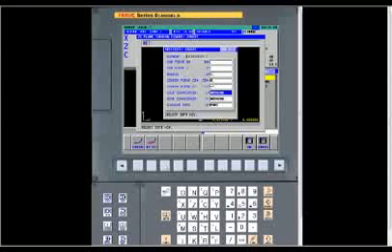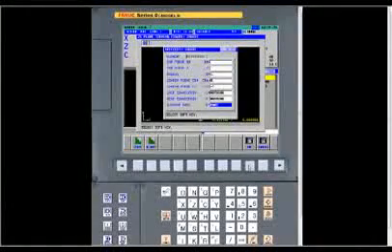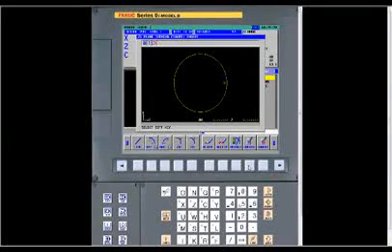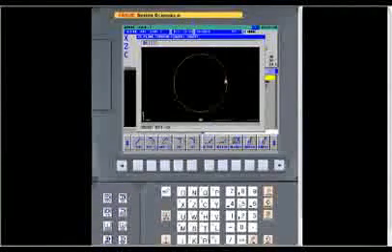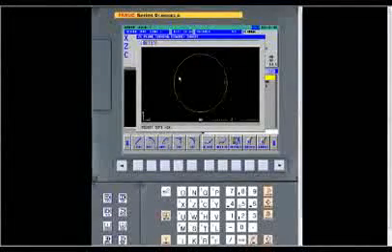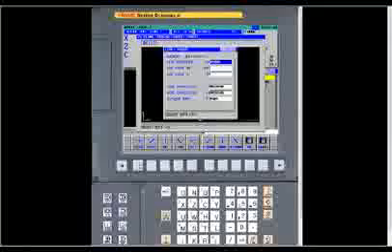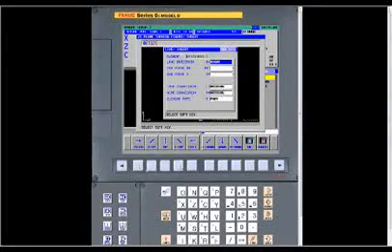And again, nothing in the next 2. And then the element type is the part again. And when we press OK, you see it draws a complete circle. The blue line is the straight line that we described. And then this is the circle. And the reason it drew a complete circle is we didn't give it any endpoints. And the control is going to figure out where the endpoint is based on what we do next. So at this point, we know that there's a line that's going to the left.